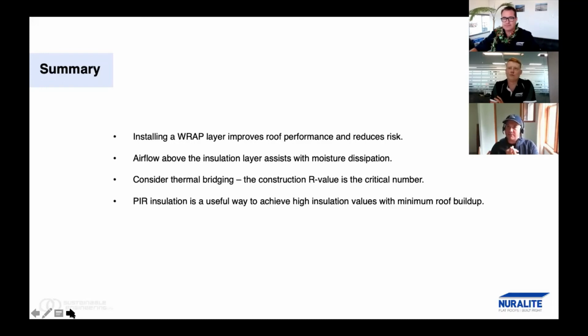Then there's the calculation method, where you can offset for a certain glazing ratio on homes. You're allowed to say, oh, I'll make the roof a little bit thinner and I'll make the wall a little better. And you can do a simple hand calculation with pencil and show it's good enough, right? And then finally, there's a modeling method. It's something we didn't talk about because we were just talking about the schedule method here. But in the new H1 code, not the acceptable solutions, but the verification methods, they've got a modeling methodology. In that, you can model a building that's built as per the schedule method, and then a building built the way you're actually going to build it and show that the whole building meets the standard.